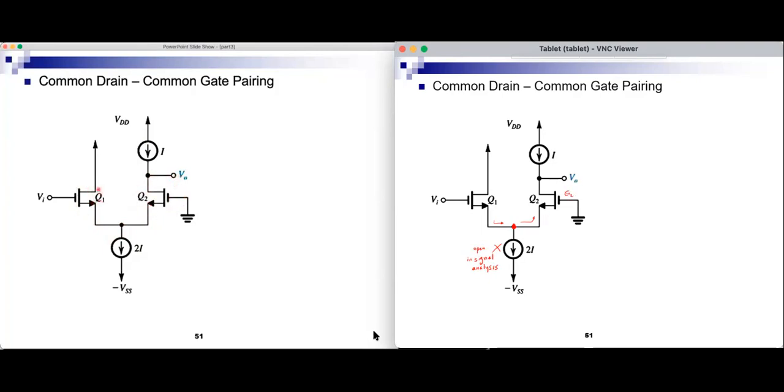So this is the common drain, input here, output here, intermediate output here, with drain at signal ground, and then the input goes to the source of Q2, the output taken from the drain, and this is the common gate. So this, in fact, is common drain, common gate. And what is the advantage of such a configuration?